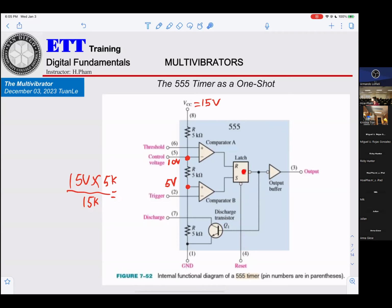You understand output Q here, depending on R and S, can be at logic 0 or at logic 1 here. So when Q equals logic 1, Q1 will be turned on. And if Q equals 0, Q1 will be turned off.